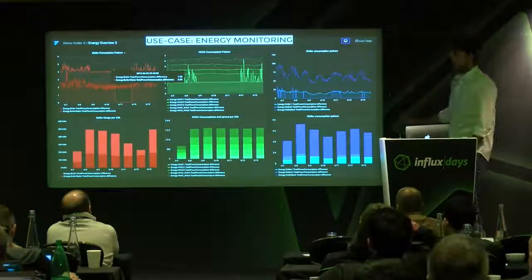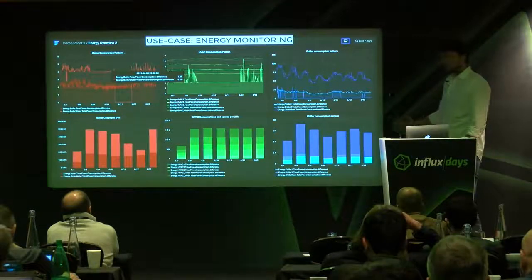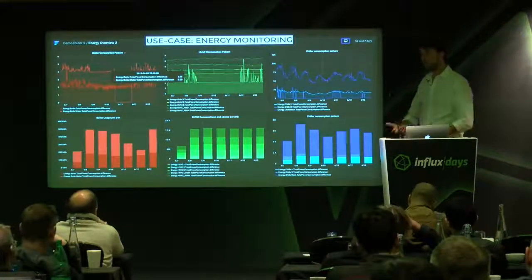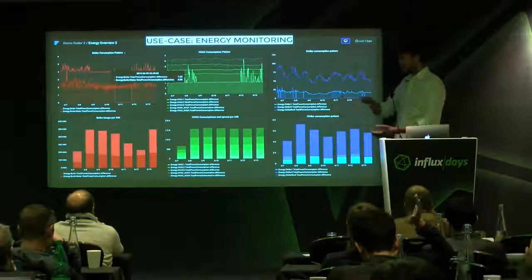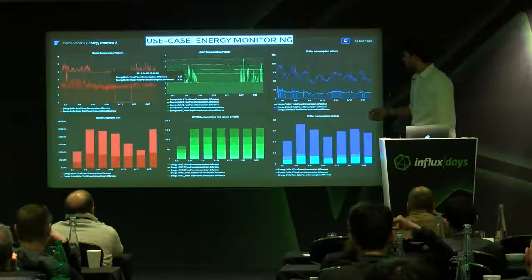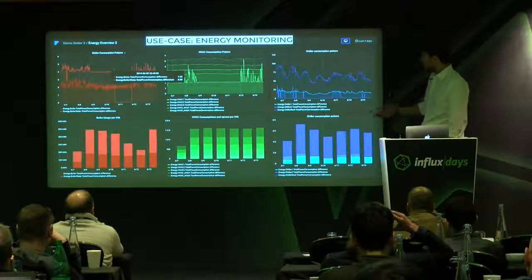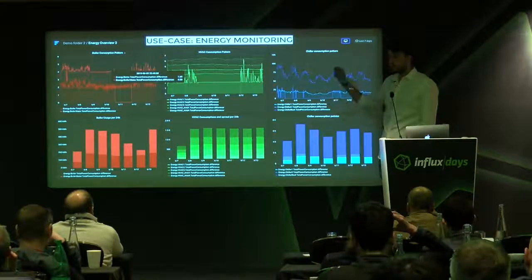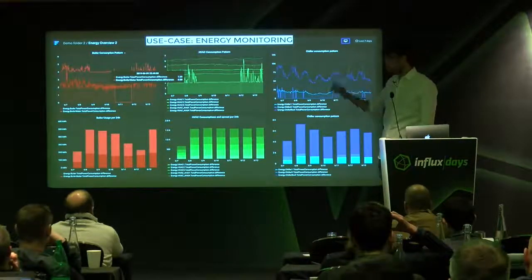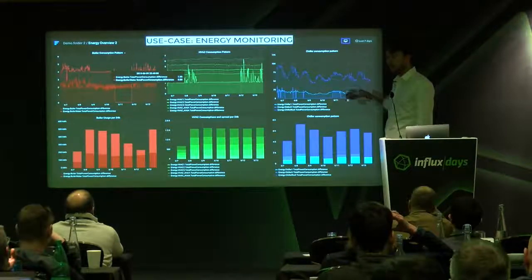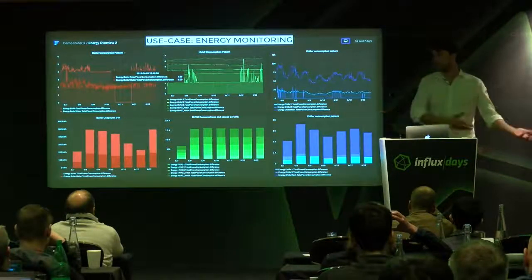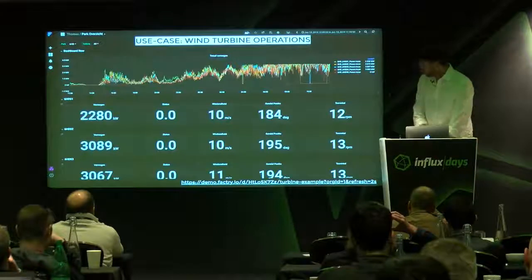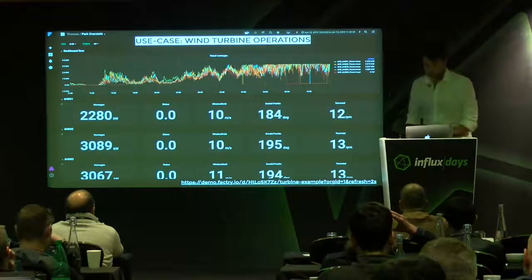Another one is energy monitoring. So most factories already have a lot of energy sensors, power sensors, that kind of stuff installed, but nobody's doing anything with the data. So when you just start, these are counters, so kilowatt counters and usage counters, they just go up and up and up all the time. But if you use some of the InfluxDB query functions, to calculate, for example, differences on minute base, you can really get consumption patterns from them. So you can already start learning new things from data that was available somewhere, but nobody was using it.